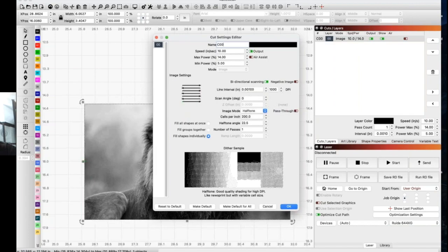All right, and of course in LightBurn we do have the ability, depending on what we're engraving, to change the negative image. I was just doing a photo on glass, so some of my settings here are pretty high. We'll change this down for speed purposes.